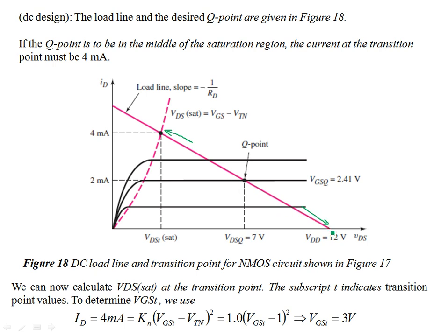It can be chopped off. For example, the crest could be chopped off if it is around the cutoff, and you might not have the maximum amplitude. Similarly, the lower region of the amplified sinusoid can be cut off if it is near the non-sat region. So preferably the Q point should be somewhere in the middle of the load line.